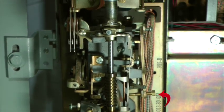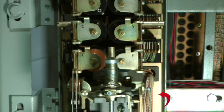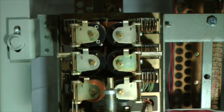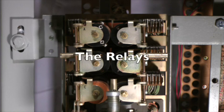The vertical rear mounting plate that runs the length of the line finder is called the switch base. The cover plate, the switch frame, and these 6 relays are all attached to the switch base, although they are attached through insulators so that they will not be grounded by the line finder shelf framework. There are 6 relays designated as A, B, C, D, E, and F. We'll be describing their operation in detail when we progress through a dial tone request. For now, I'll provide a brief overview of each of the relay's functions.